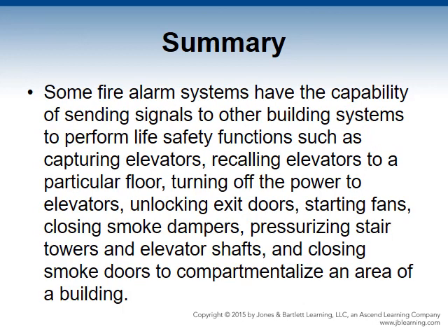Some fire alarm systems have the capability of sending signals to other building systems to perform life safety functions, such as capturing elevators, recalling elevators to a particular floor, turning off the power to elevators, unlocking exit doors, starting fans, closing smoke dampers, pressurizing stair towers and elevator shafts, and closing smoke doors to compartmentalize an area of the building.